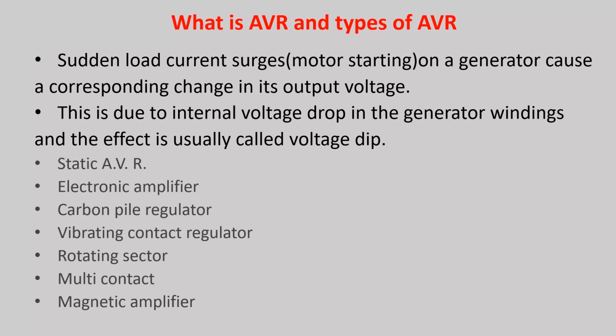We can normally see this in our home also, in the evening when we all put on the fans or ACs at the time of summer season, there will be some fluctuation in the voltage. That is the normal thing, no? That is the normal fluctuation, that is called surges. So this cannot be prolonged. We cannot use it with low voltage or high voltage. Plus or minus some percentage is okay for the equipment, but we cannot let it run for a long time, because the torque and flux will vary and that will damage the windings.